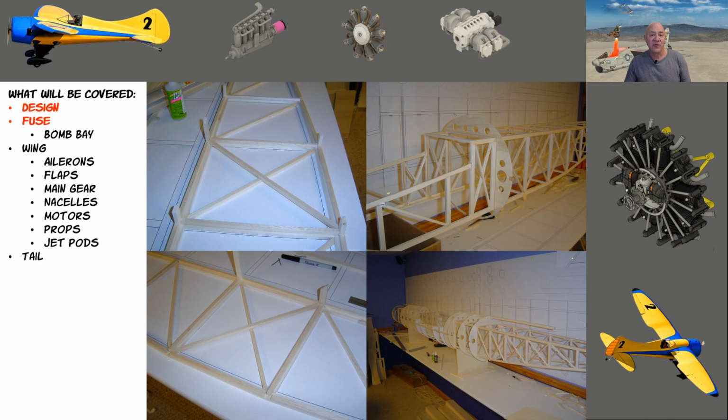What I learned really quickly is that we way overbuild model aircraft. We had to back in the day because we had either a glow or a gas engine that just vibrated. I mean, it would just shake planes. So our mentality was always to build a strong enough plane. Plus, you want to have it so if you have a hard landing, you're not going to damage the airplane.